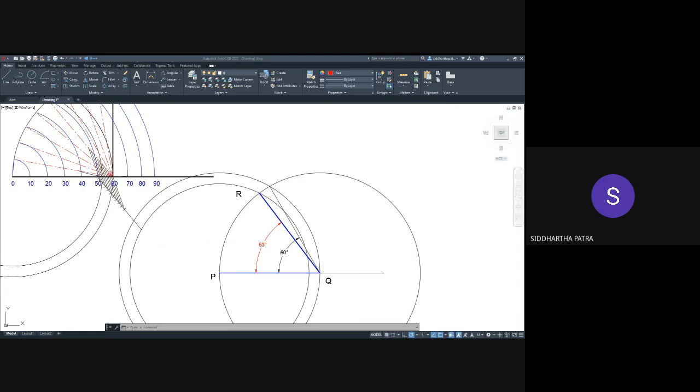That way you can first draw a 60 degree, then draw a 120 degree. You know how to draw 120 degree, right? So basically that is just another 60 degree. Then you bisect the span between 60 and 120 degree to draw 90 degrees, something you have done various times in your school level, right? So you know how to draw a 90 degree using scale and compass, right?